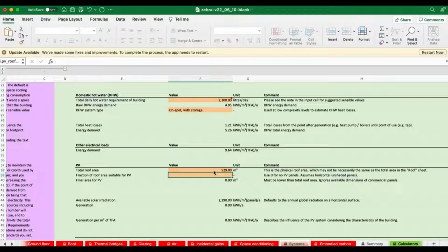Now, you can't just cover a horizontal roof solidly in PV. Your PV is not likely to just be horizontal for one. It's likely to be in frames, inclined at a certain angle. And we don't know how much space is going to be needed to walk between the frames, etc. We don't know what else is on that roof to get in the way. But we're just going to say 60% of the roof can be used for PV.